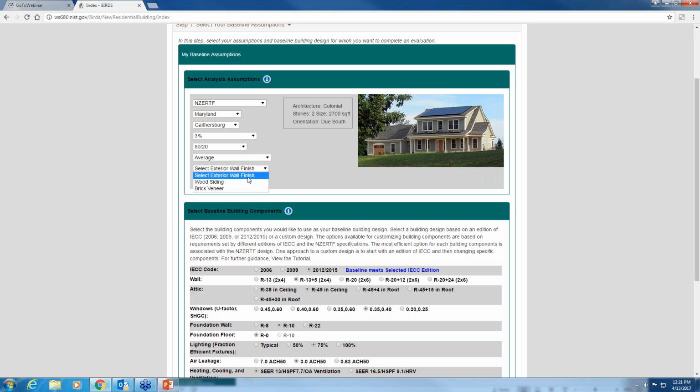And then also we've incorporated in the option for either siding or brick veneer. I would note that at the moment we're modeling wood siding, but with regards to the actual energy performance, whether it's wood siding, vinyl siding, or cement board, the relative thermal performance impact is so minimal that it's simplest to just assume that the wood siding represents all those different siding options, because the insulation component is actually separate from this finish option selection. And I'll talk a little bit about the wall insulation here momentarily.